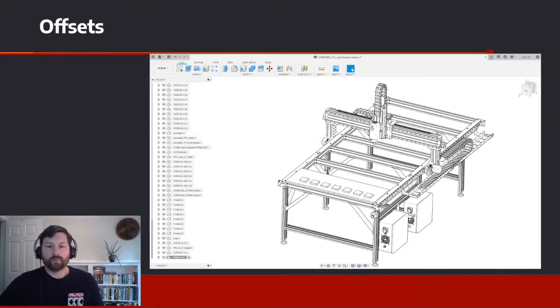And so we are going to be using a sample project today, and this is a quick example of what a machine would look like. It has 7 3.5 by 3.5 inch squares attached on the spoil board. So I'm not going to talk about work holding in this discussion, and so these are just 7 pieces of material. Let's say they're double stick taped to the machine bed, and they're in known locations. And so we had some type of measuring or way to put them in specific spots on that spoil board.